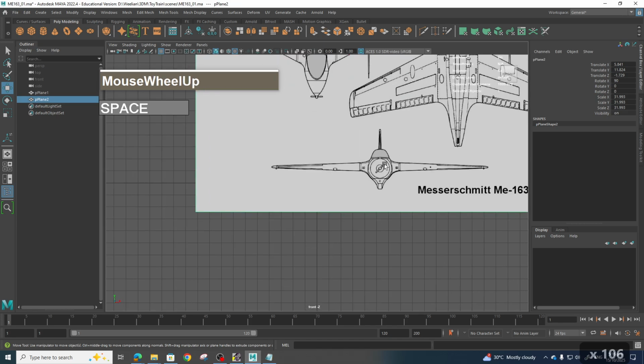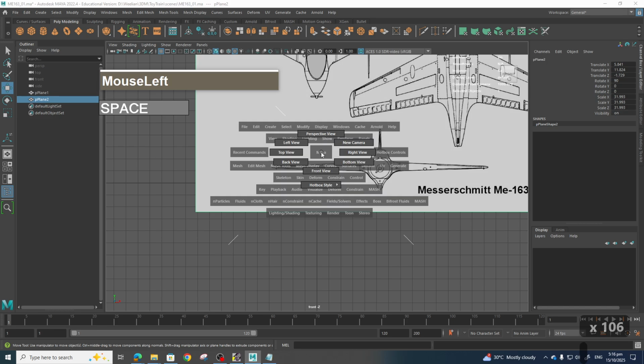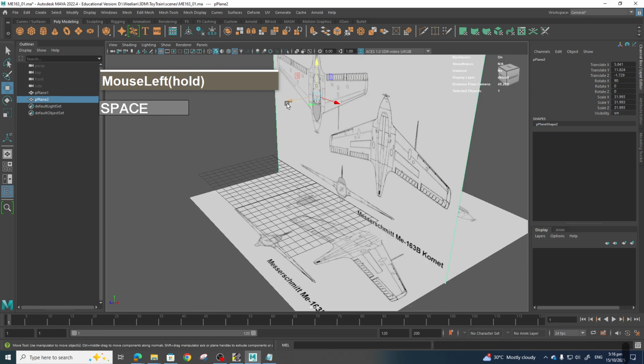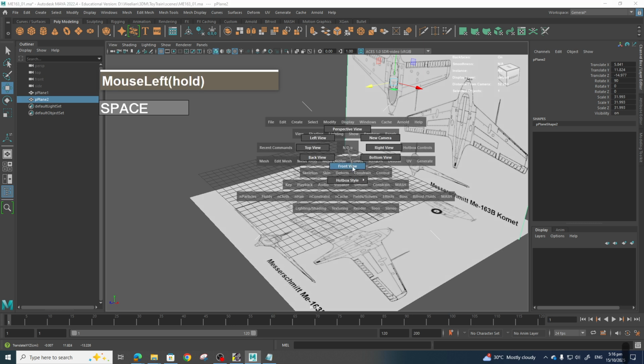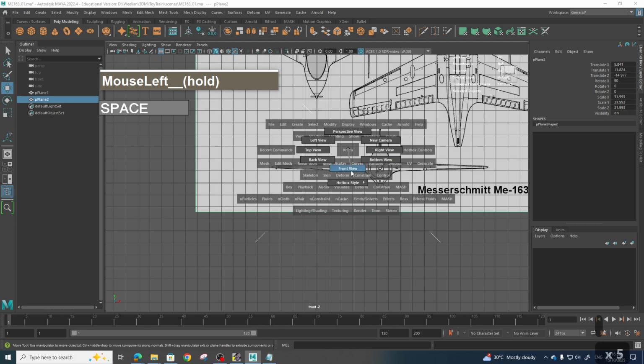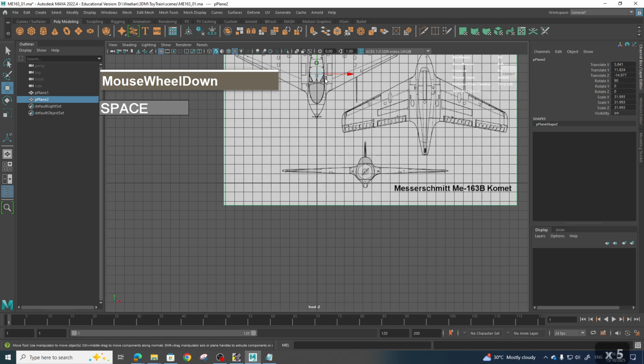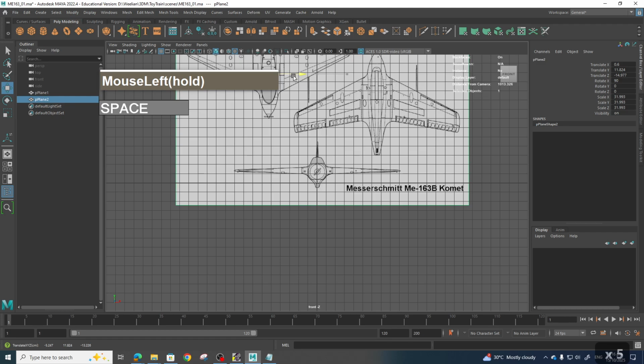Okay, right now I don't see the grid lines over it, so I need to switch back to my perspective view. I'm going to push back until it is behind the thick line here, then change to my front view again. Press my space bar and then change to front view. Then now move this view until it is right in the center like that.